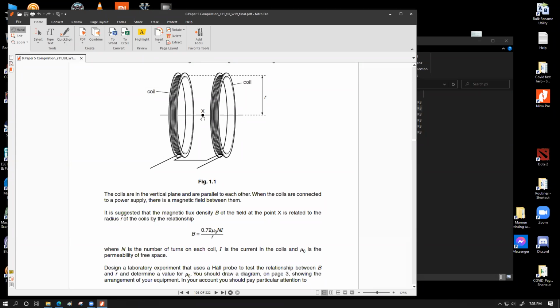One other important bit for the precaution is that since we're going to work with coils of wire and we're going to have some significant current, if the length of the wire is quite small and the thickness of the wire is not that large, then there is a possibility of significant heating in the coil. So we should preferably keep the current value flowing through the coil pretty small to begin with, so that we do not have too much heating in the coil. Yet the current value has to be strong enough, or we can increase the number of turns in the coil so that we can have a significantly strong value of magnetic flux linkage, not too few turns, like 2 or 3 turns. No, preferably go for, let's say, 10-20 turns, so that you can have a large resistance.